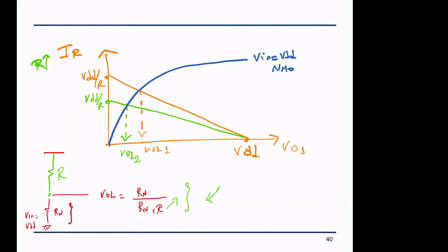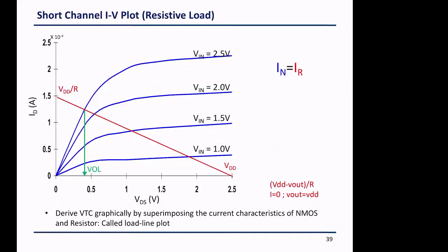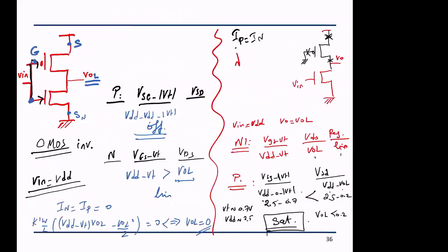Okay, because we designed the PMOS so that the resistance ratio, if I'm solving for VOL, which will give me Rn over Rn plus Rp, we design the ratio of the two transistors such that when this is on, it is closer to zero. It is bulky, it is slow, it has a large RP.